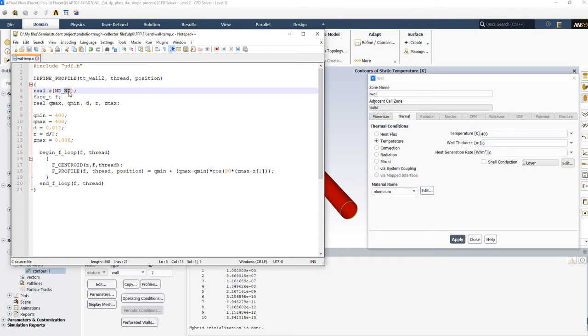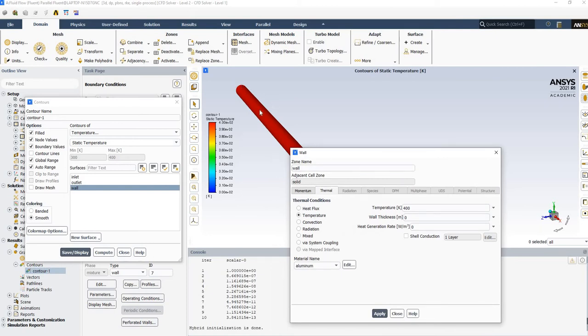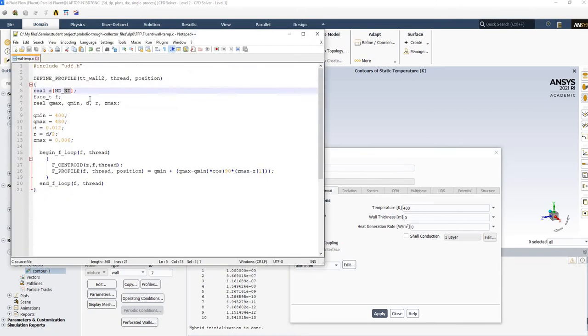If you put 0, that is only going to store the x coordinate points, along these values. If you put 1, this is going to be the y coordinate point. If you put 2, this is going to be the z coordinate point. So we have only 3 coordinates in here. If it's only 2 coordinates, then you can only apply 0 and 1. This problem has 3 coordinate points, x, y, and z, so either 0, 1, 2.